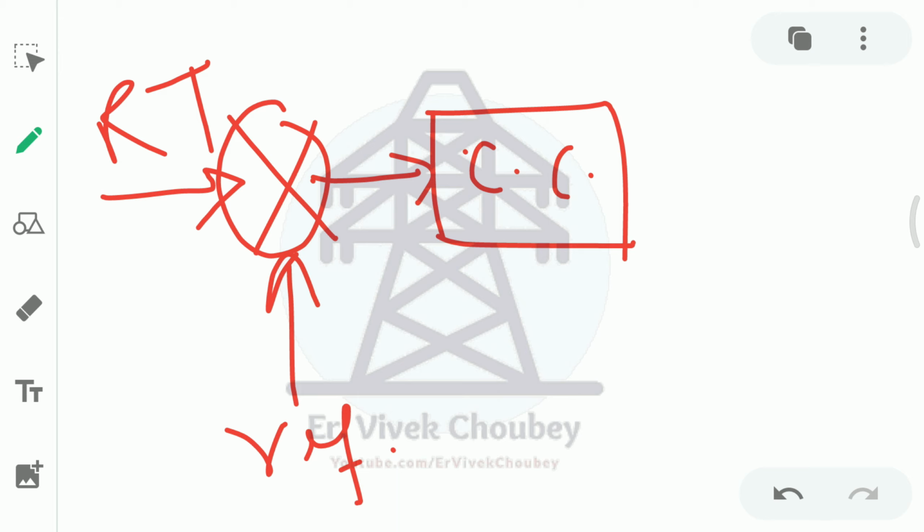Now what happens here is that in a non-inverter AC, this comparator output is fed to the compressor input. As soon as a difference of temperature is seen by the compressor circuit, like in this case there's a difference of 5 degrees Celsius, it will turn on the compressor. Turning on the compressor means turning on an induction motor. As you all know, an induction motor works like a short-circuited transformer during start. During start the slip of an induction motor is 1, and it behaves like a short-circuited transformer, and hence it tries to draw a huge amount of current from the line.